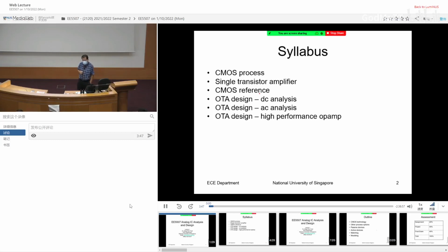And the third lecture, we are going to look into references. How do you generate a reference? In circuit design, a very important thing is the reference voltage. For example, in an ADC, how do you know that at a certain voltage it is 1110? Because you have the fixed reference, right? How do you know that the circuit always functions as it is without change, that the regulator output is always 5 volts? You need to create an accurate reference. Usually it is a voltage reference. It could also be a current reference, since in a lot of circuits we need a current source.